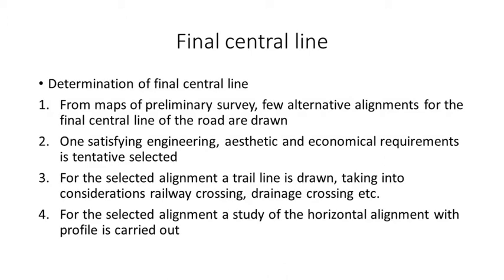Okay. And next one is the resources available. So whether the resources are available or not. That information you also check: the local available contractor, water availability, labor availability, material availability. So all these resources information should be collected in the reconnaissance survey also.